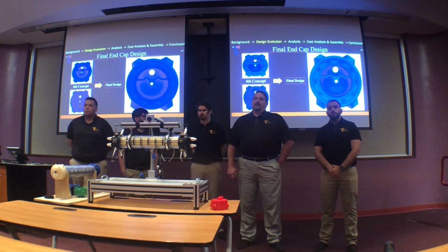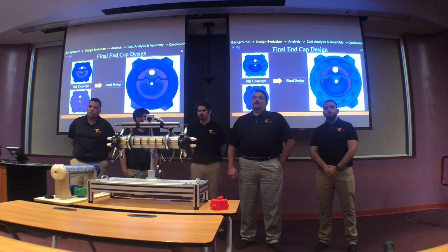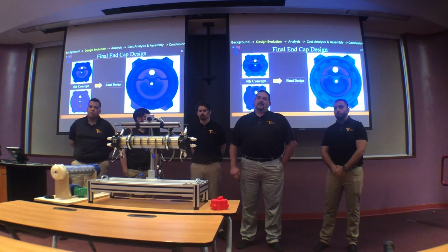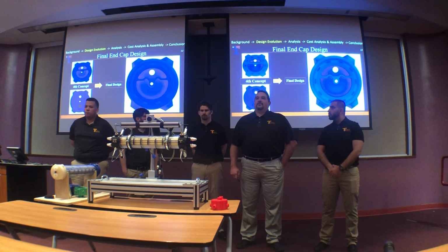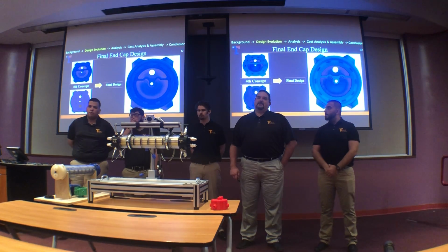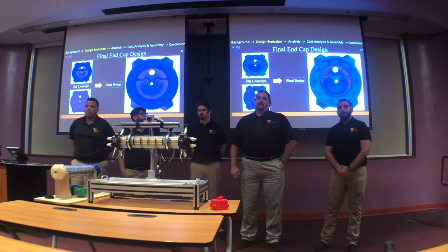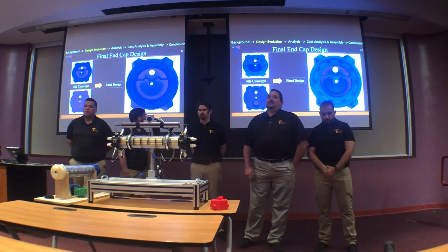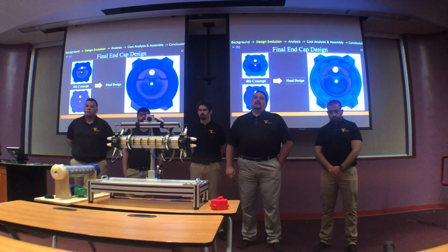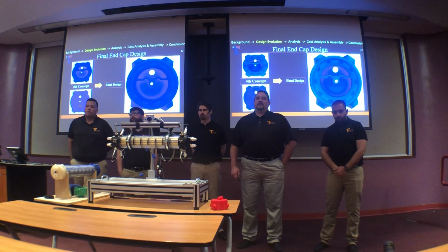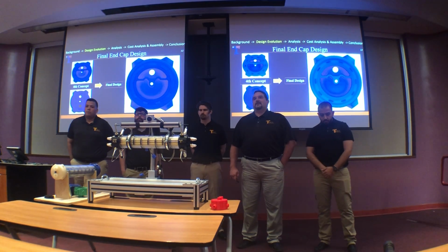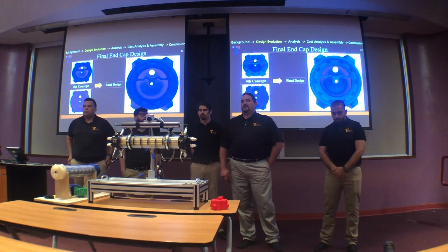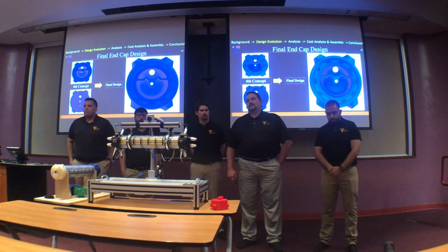And we also kicked around the idea of how we could incorporate a larger number of tubes within the shell and tube heat exchanger. And if you can see in our final design there, we just made a small change on the divider between the two chambers. And by doing this, we're able to incorporate 18 3/8-inch tubes or either 6 3/4-inch tubes in the design. You can use either one, interchangeable material, whatever kind of material you want to put in there.